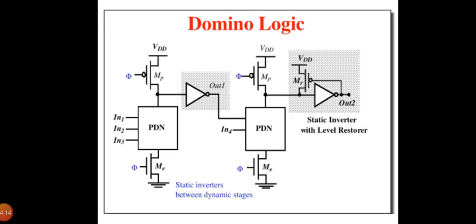If the primary input N1 is 1 during evaluation, the output of each dynamic gate evaluates to 0, and the output of each static inverter is 1. On the falling edge of the clock, the pre-charge operation is started. Assume further that N1 makes a high to low transition. The input to the second gate is initially high, and it takes 2 gate delays before N2 is driven low.